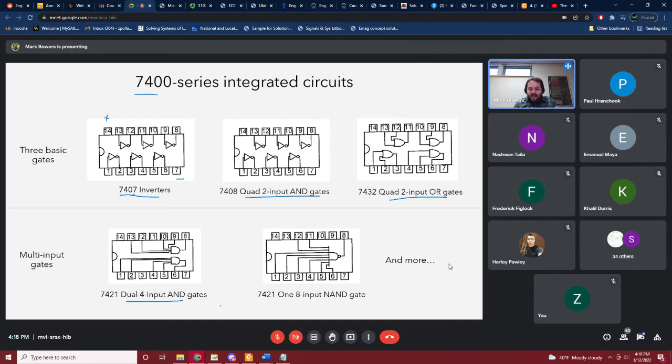Well, one way of doing that really simply is you get a comparator, and you would use the comparator to find out, okay, have I reached the right voltage on each of the 3 power supplies? And you can take those 3 comparator pins and run them into an AND gate and see, are all of them high? And then you'd know all of my power supplies are available. Just as a simple example.